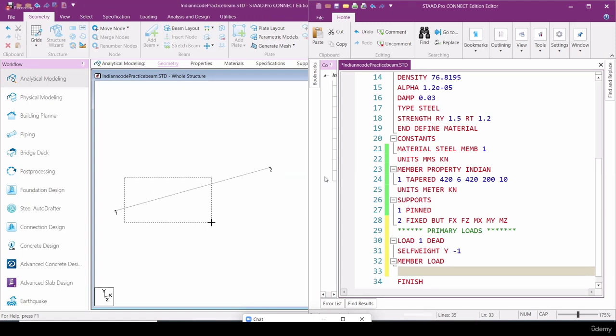This is a member, right? Generally we know this is a beam, but STAAD will consider it as a member. For the member number, if I click Shift B, it is showing 1. If I suppose I'm turning on node numbers here, Shift N, it is showing member number 1. So I have to denote 1, and then the syntax will be UNI GY, suppose -2.